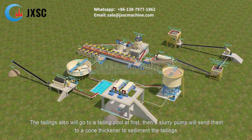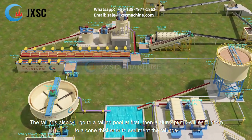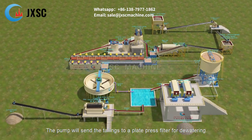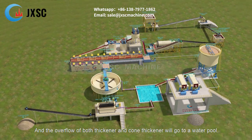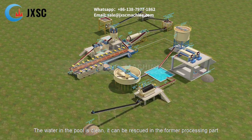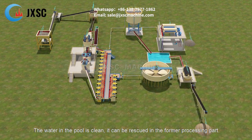The tailings also will go to a tailing pool at first. Then a slurry pump will send them to a cone thickener to sediment the tailings. The pump will send the tailings to a plate press filter for dewatering, and the overflow of both thickener and cone thickener will go to a water pool. The water in the pool is clean. It can be reused in the former processing part.